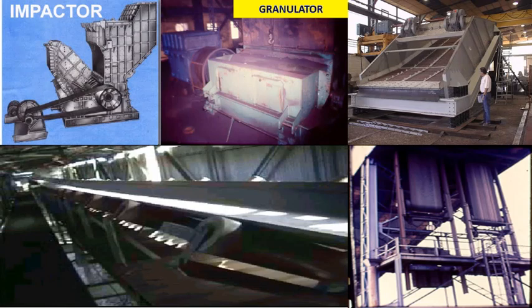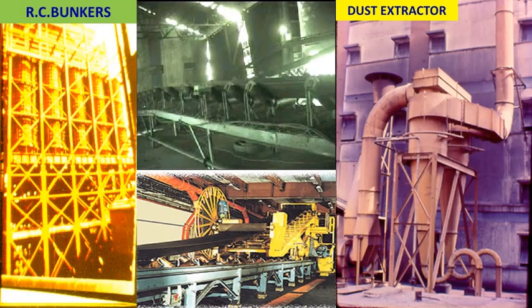There are granulated crushers, and these crush the coal into minus 20 millimeter size, and we have an arrangement to separate the coal fines generated during crushing and fragmentation. Except for this coal dust, the crushed coal below 20 mm size is taken further by a conveyor system to the raw coal bunkers.